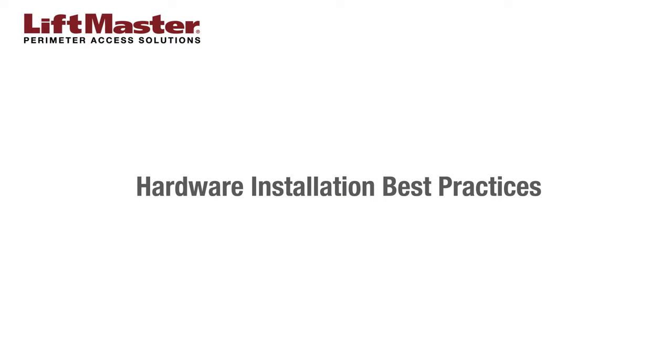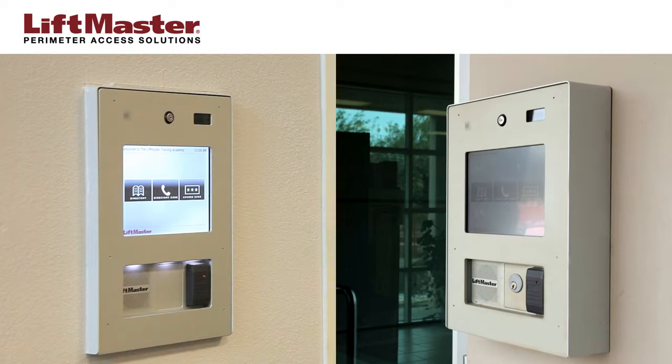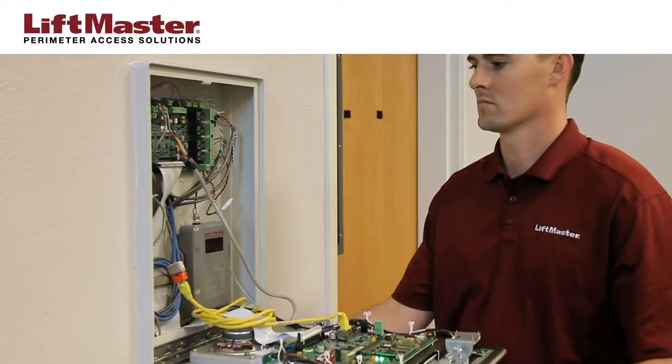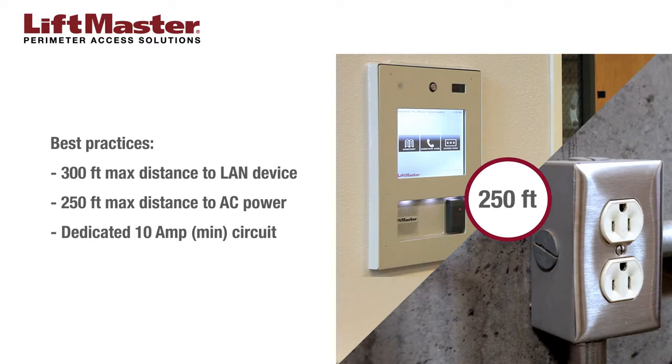Best practices for hardware installation include the following. The IPAC can be mounted indoors or outdoors, but is for surface or recessed mounting only. Make sure there is clearance for the cover to open freely after installation is complete. Install the IPAC in a location within 300 feet of the LAN device to avoid issues caused by network cable limits. Power the IPAC using a dedicated 120-volt AC outlet located within 250 feet of the access control panel.